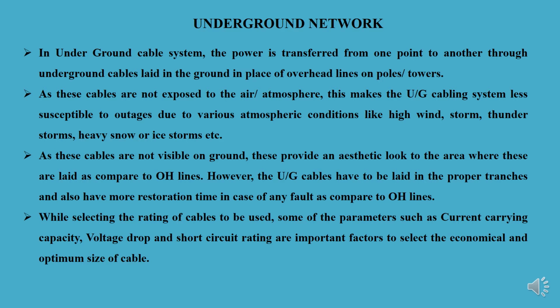Voltage drop is also important. Short circuit rating too, as there are chances of short circuit below the ground also. So these are some factors while selecting cables for below ground loads. It should be economical, and we have to choose the optimum size of the cables.